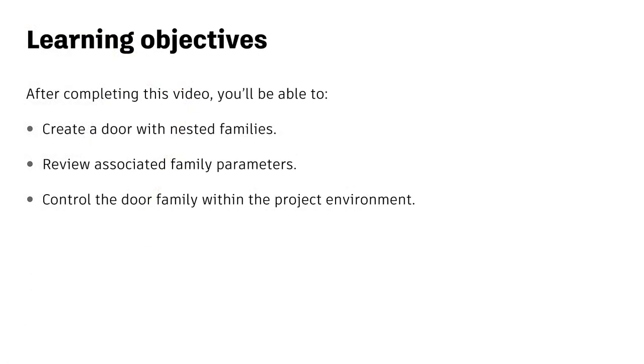In this video, you create a door assembled from nested families. This is the most efficient method of creating complex families, as each of the family elements can be controlled more predictably by associating family parameters. Also, the family elements can be reused within other families. You also review the associated parameters and finally test the family within a project.